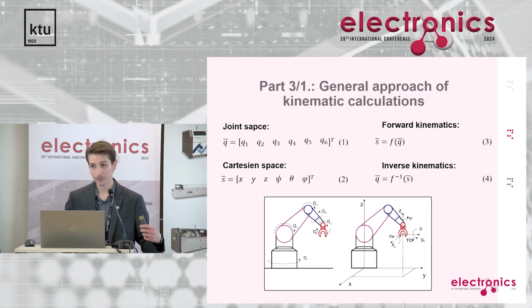Continuous calculation happens between the two kinds of coordinates during the motion of the robot. If a division by 0 can occur, it cannot be performed. In this case, the controller will lose control of the robot, and this is when singularity happens.